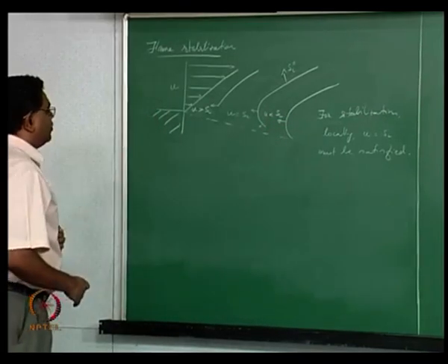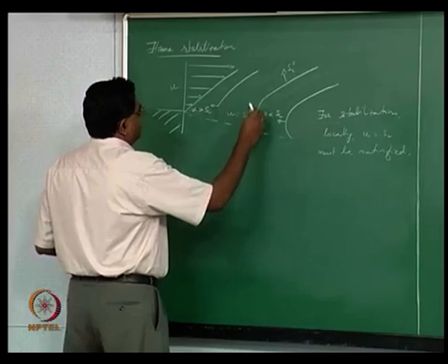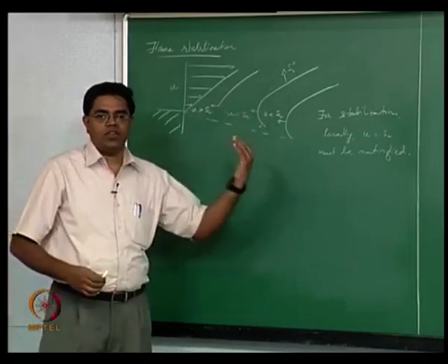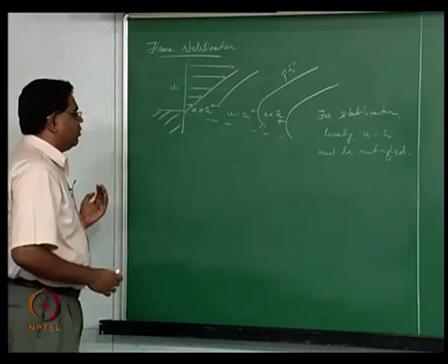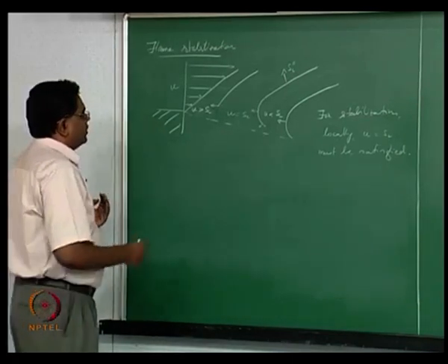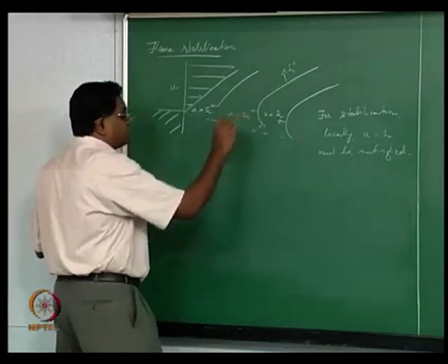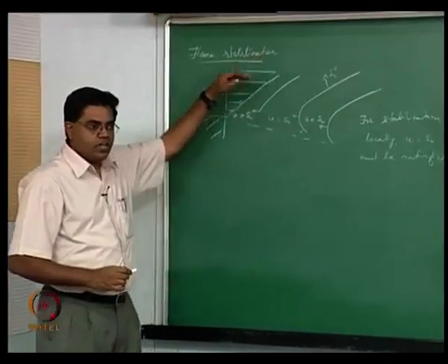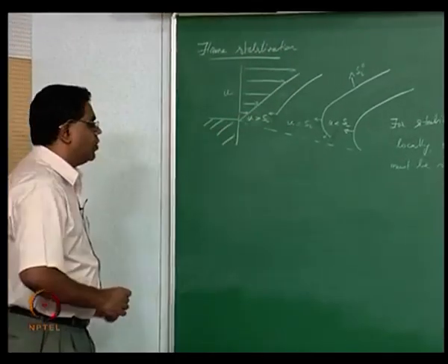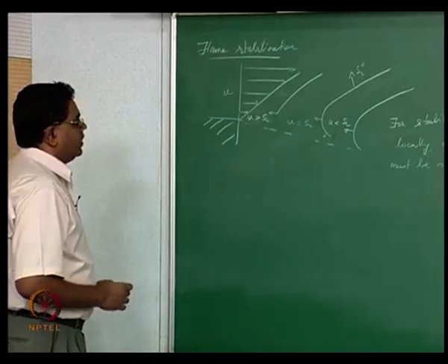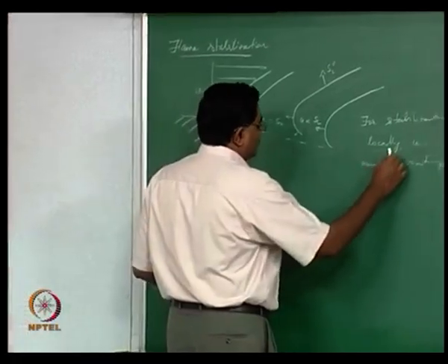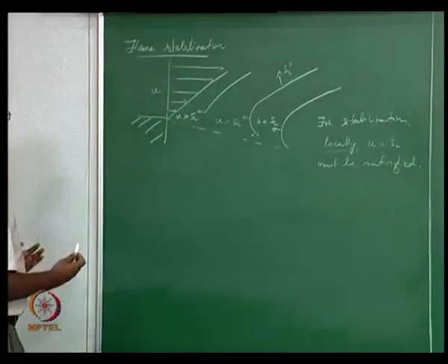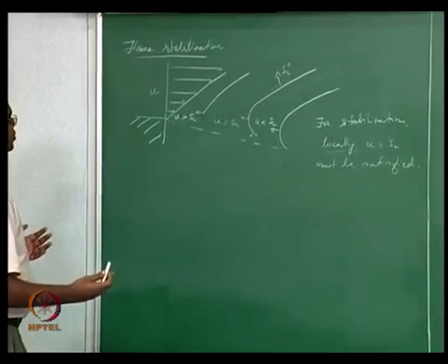What we are basically looking for is a leading edge of the flame which has a slope perpendicular to the flow, where the SL has to match the velocity directly. We are looking for a condition where the local SL has to match the local U. Since the U is also increasing linearly, the flame stabilization condition is that locally we need to have this matching satisfied.